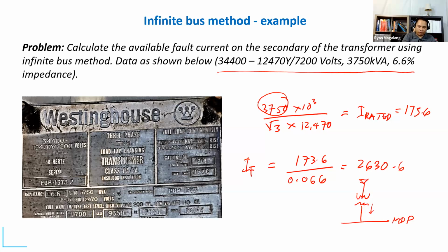When you're designing something, the default answer is to say, oh, I'll just put something bigger here so that I'm safe, making sure that I'm not overloading the transformer. But just because you're able to put a big transformer in there doesn't mean you should do it, because what it does is increase the available fault current at that point.